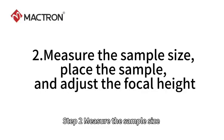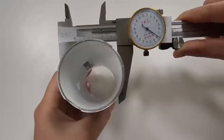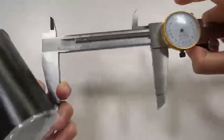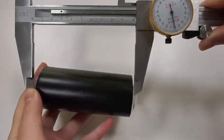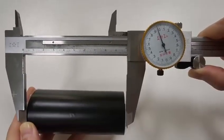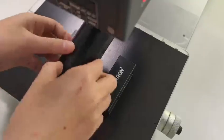Step 2. Measure the sample size, place the sample, and measure the focal height. Take a sample and measure its diameter and length. The diameter of this cylindrical sample is 44.9 millimeters. And its length is 100 millimeters. Place the measured sample on the marking platform.